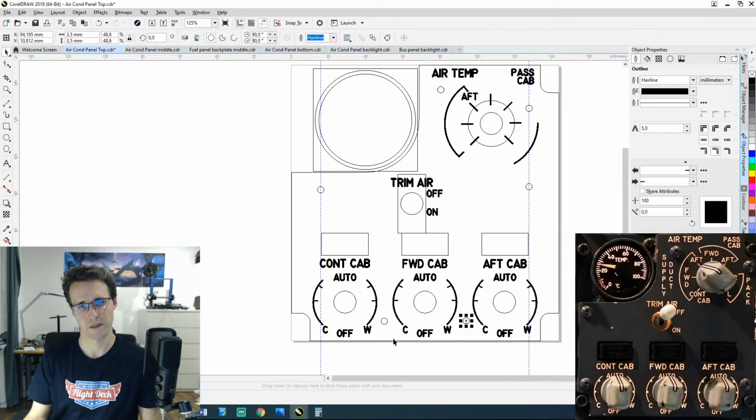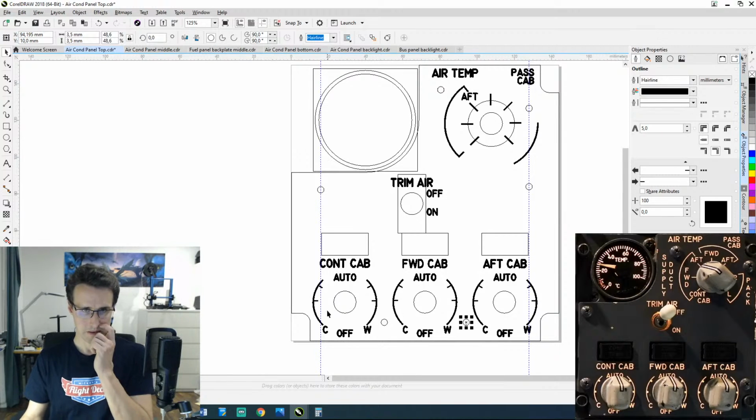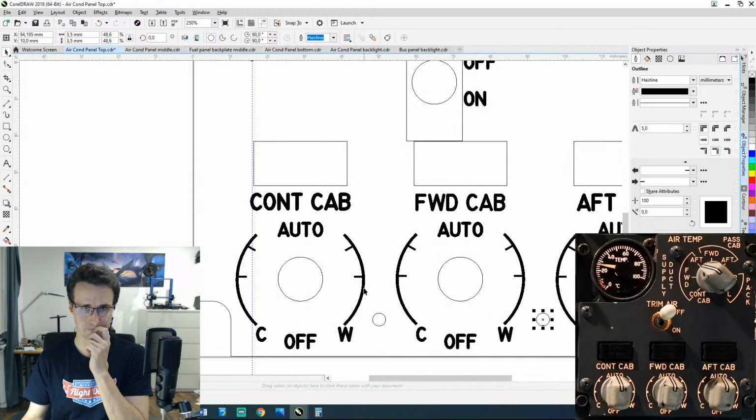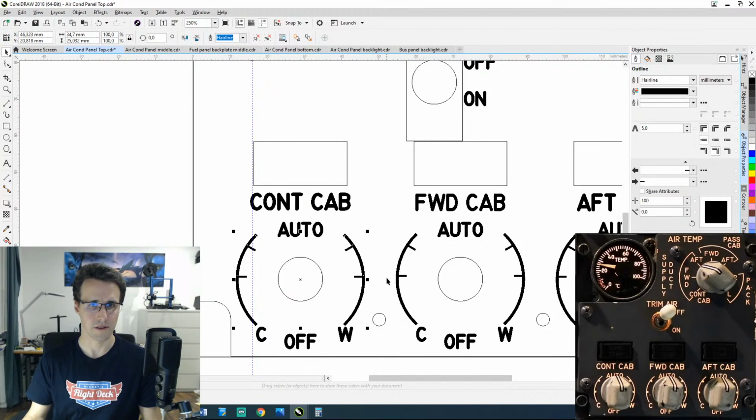And now here at the bottom, we don't need to leave the 16 millimeters. Here we can come nearer to this edge. I think these 10 millimeters from the bottom is good. 10, and here also the 10, and now we can align them a little bit better between these two here. We can do this. Calculate the distance between these two here.